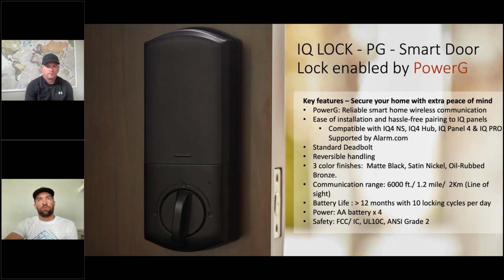I've talked to a few dealers, and when you're looking at that, you kind of have to factor in service calls for Z-Waves, right? I come from the dealer world, and I know that was a constant headache for some of the companies I worked for. But you also have to consider the cost of the mesh for Z-Wave and worry about repeaters and making sure that they can communicate back, right? Typically, the doors are installed at the end of the house, the front door, the back door, in the garage, far away from the panel. So that's always been an issue where we're adding in repeaters, checking the mesh signal strength, and doing things to try to make them communicate reliably. With the PowerG door lock, we don't have to do that anymore, right?